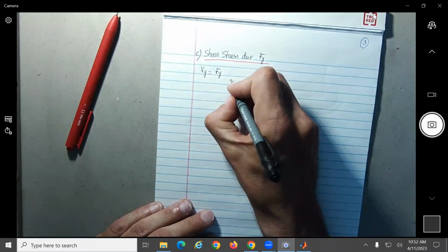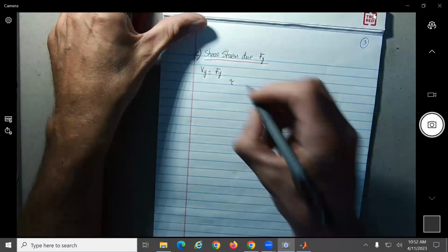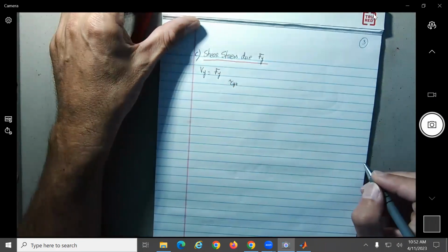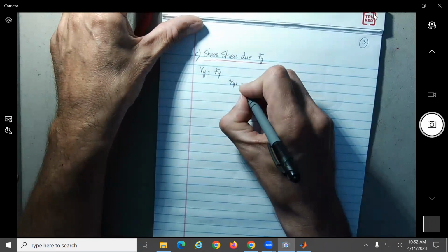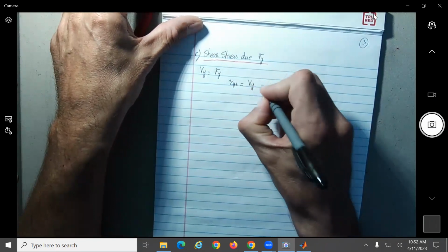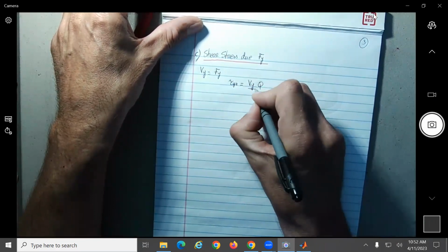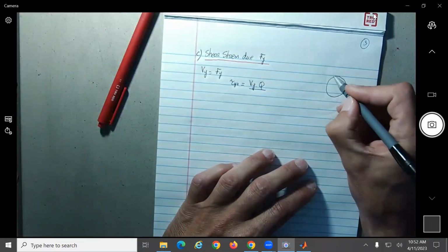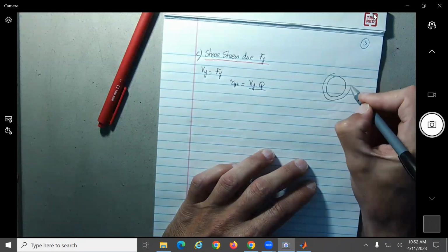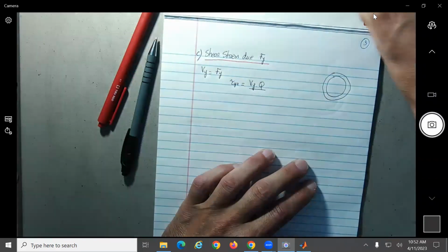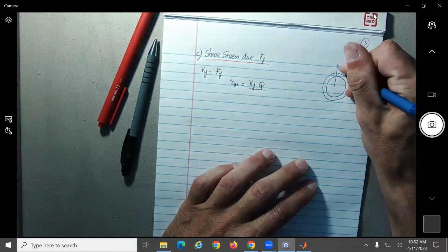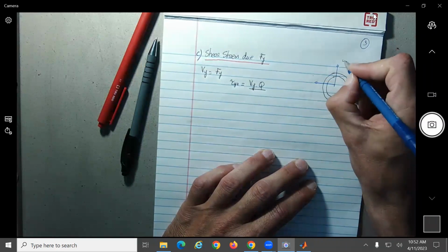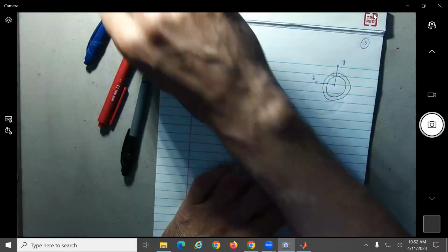And in this case, you want to be accurate, you should have one over here, times of what? Tau YZ, no, because it's in that plane, should be equal to Vy times the Q. And this will be going on which axis? Here it doesn't matter really because they are the same value, but if you needed to put the letters, so this is YZ, we're looking at the force Vy now.